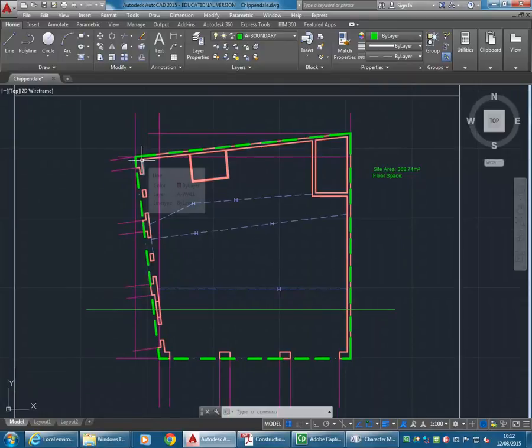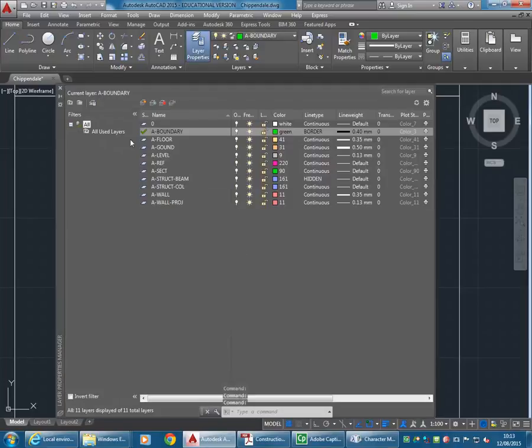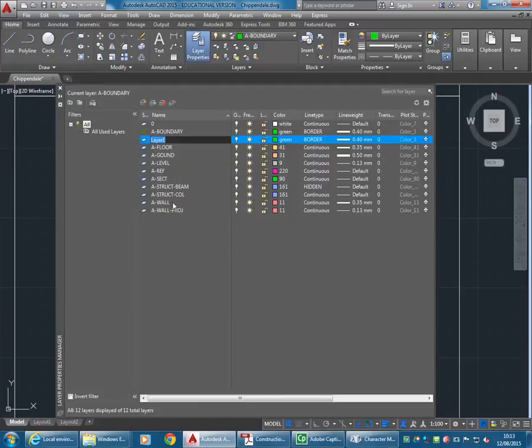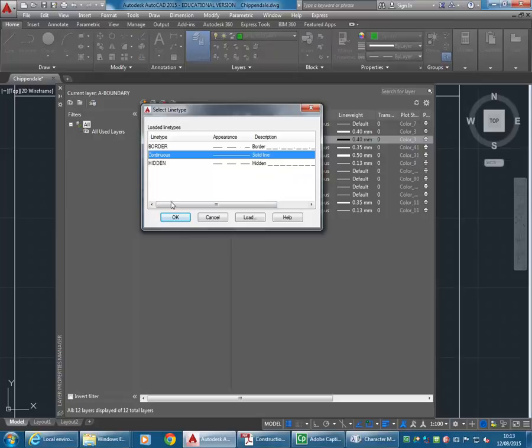But one common method is to do it from the inside wall, inside of the wall face. Council often will tell you it's got to be from the outside of the wall, but just to show you something different, I'll do it from the inside. So here you can just make another layer, floor area, I'll call it, and we'll turn this layer off once it's been used.